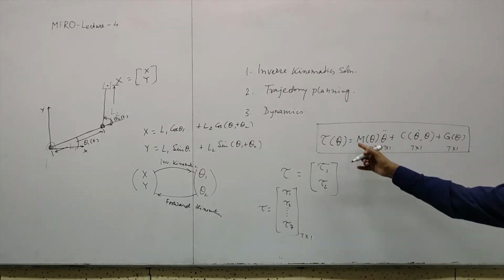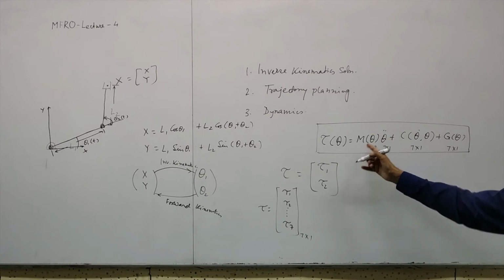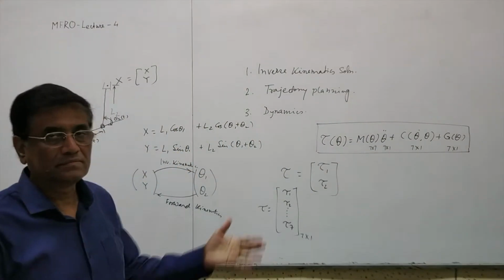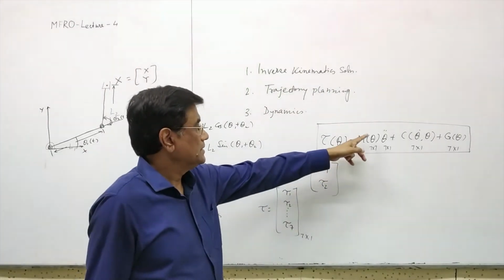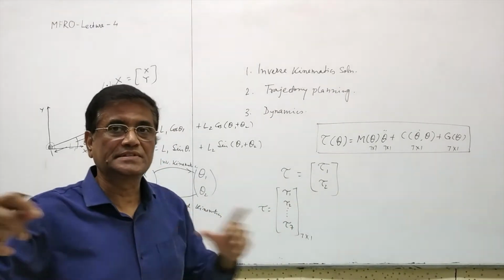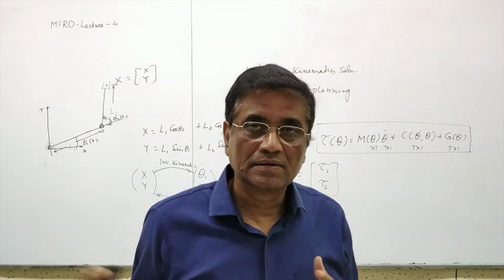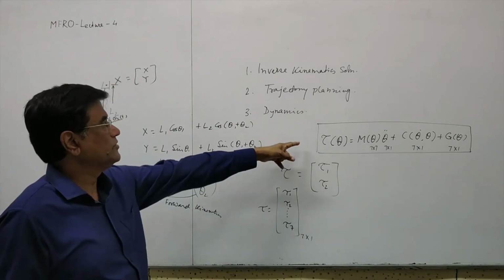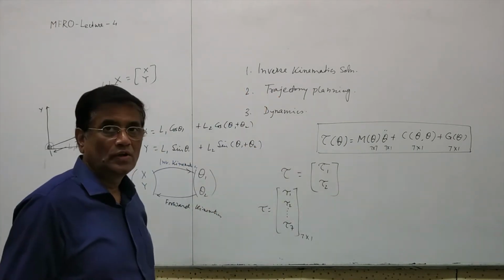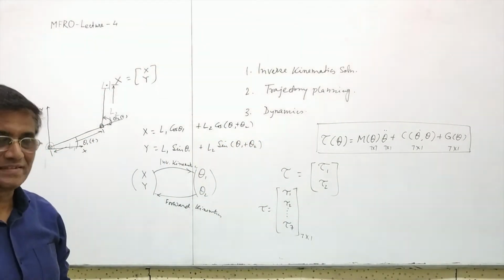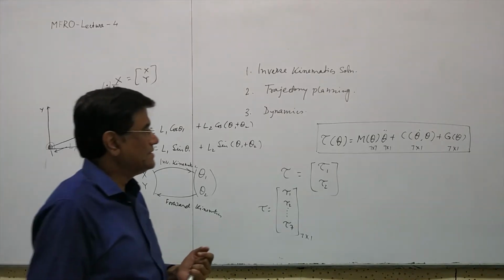So this is called the mass matrix or inertia matrix. This is actually also a tensor. There are so many names. This is a matrix. It represents how the mass is distributed in the robot. And this is very important for the dynamics equation to be solved. Here also the concept of forward dynamics and inverse dynamics exists. Now let us try to understand what that is.